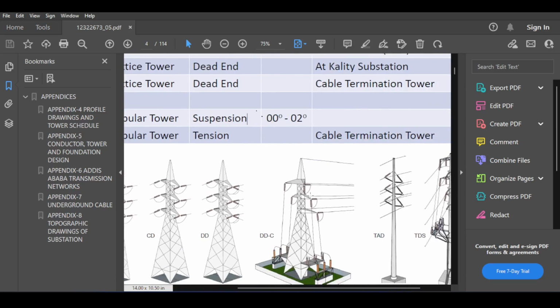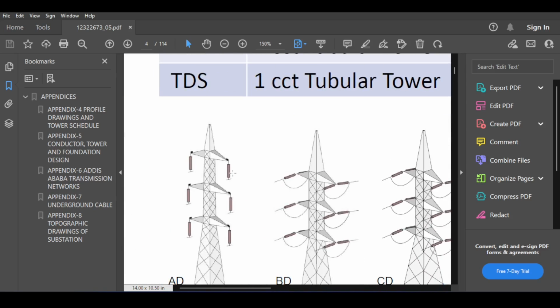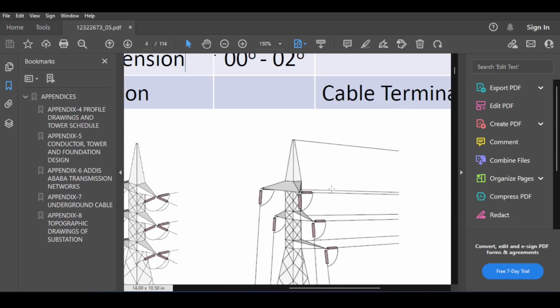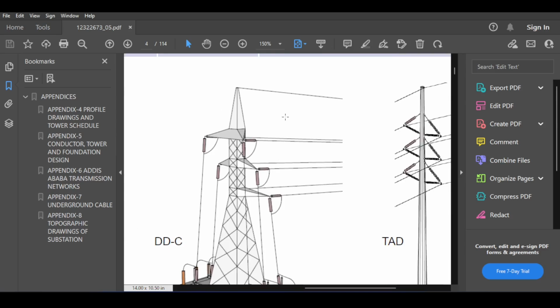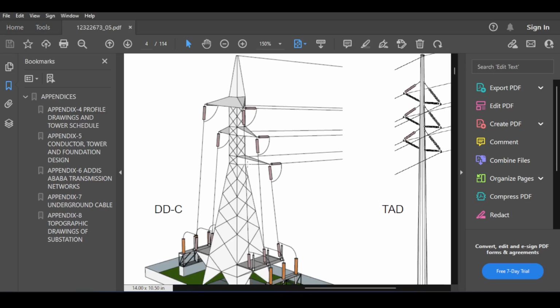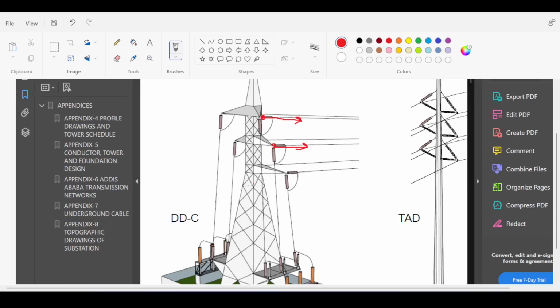And this is a dangerous one. Those are the most dangerous towers because unlike all other towers, those towers are loaded from one side only, meaning that they feel the tension from one side but have nothing to balance or compensate for it, meaning that this entire structure will bend in the direction of the loads. So what I'm trying to say here is that those towers are basically feeling tension from one side, as you can see here, and this tension from one side will cause moments on the base of the tower.